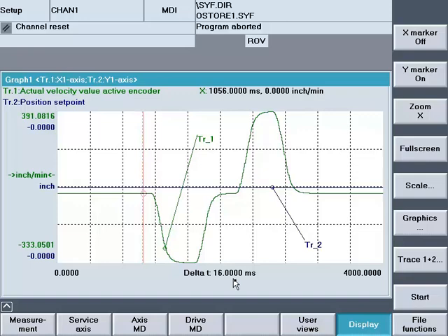So when you're setting up a trace, you have to balance out how much time you need versus how important it is to get all the high-speed stuff. Since we're logging at a relatively low rate of 4 milliseconds, if we're looking for high-speed stuff like why an encoder is humming, that's usually going to be up in a high frequency, 500, 600, 700 hertz if we're hearing it, maybe 1,000. 4 milliseconds is 250 hertz.